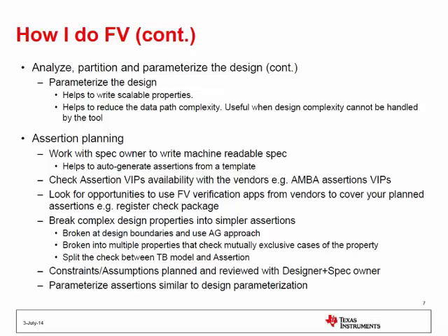So it is like a model check between your TB model and your RTL. The difference is the RTL has much more complexity involved. It may have to handle multiple clock domains, it may have to handle power domains. Your TB model is very, very simple, which is nothing but a protocol conversion. That's all it is going to do, and you can use that to directly apply a very simple property on the TB model you have built and the RTL, and then make sure it is indeed matching.